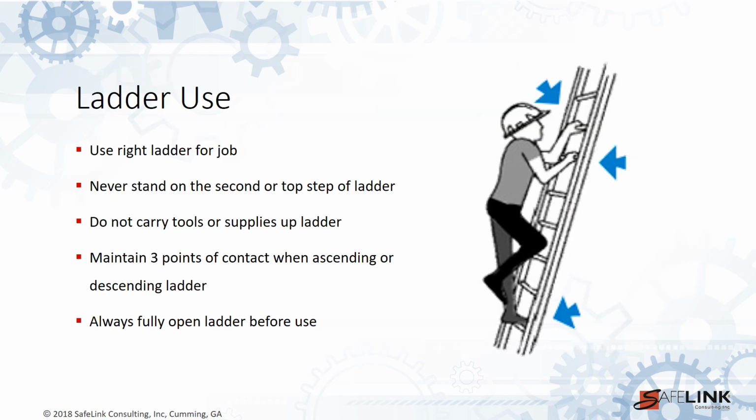If a ladder is used, always use the right ladder for the job. Ensure it is tall enough to reach the work area without standing on the top rung. Do not carry items or tools up the ladder with you. Always maintain 3 points of contact when ascending or descending the ladder. Always fully open the ladder before use.